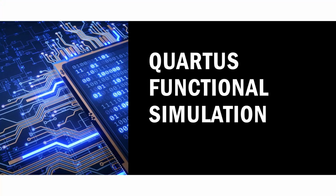Today we're going to see how to create a Quartus functional simulation. We'll use a block diagram schematic of logic gates: AND, OR, NOT, XOR, and buffer, and then create the functional simulation. Okay, so let's get started by bringing up Quartus.